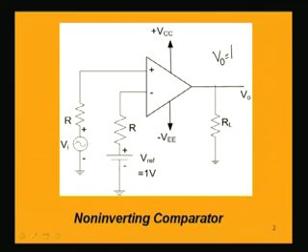It will be A, the gain of the op-amp, multiplied by the difference voltage VID, that is the voltage available between these two terminals. If I name them V1 and V2, VID will be equal to V1 minus V2. So, it is A times (V1 minus V2) that should be the output voltage.